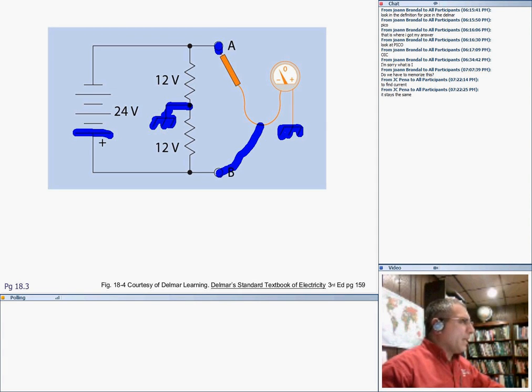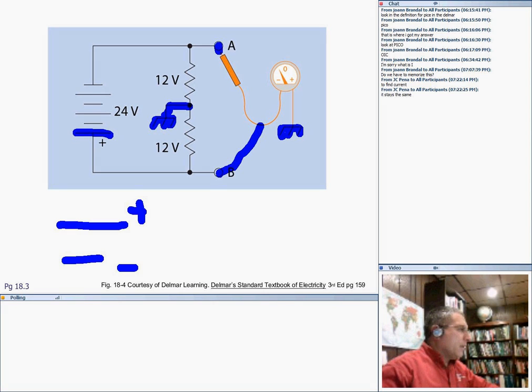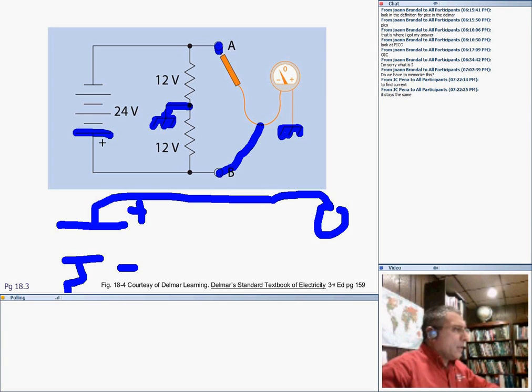Not a lot of meaning for it in the power industry, but in the low voltage industry it has a big meaning. If you have a battery, you have your positive and you have your negative. You run the negative side to your chassis, and then you grab your voltage. Here's my light; you get +24, and from the other side you can connect it directly to the chassis. So you've got yourself that reference point, the frame.